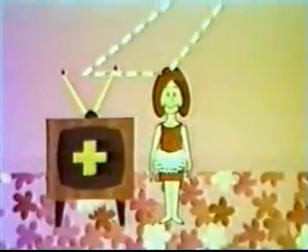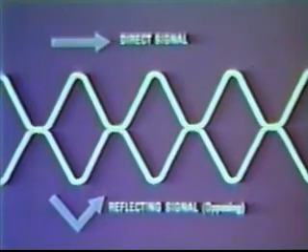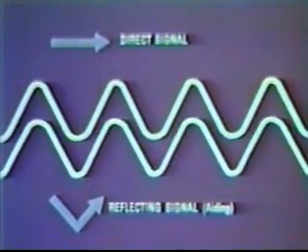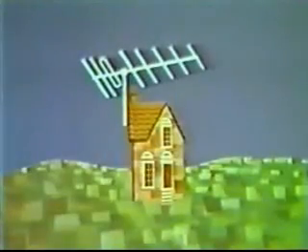Room aerials and set-top aerials will rarely give satisfactory results and may result in objectionable ghosting effects dependent on the position of people within the room. Short-term reflections can also give rise to unbalance between the luminance and chrominance signals. Repositioning the aerial may give an improvement, and the rigid mounting of the aerial is also important.